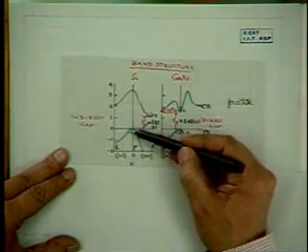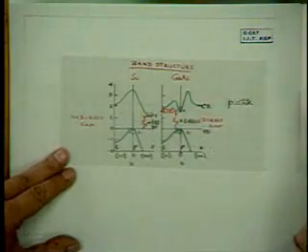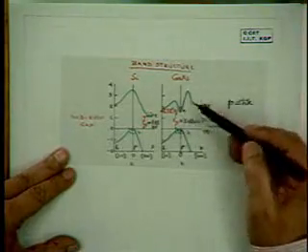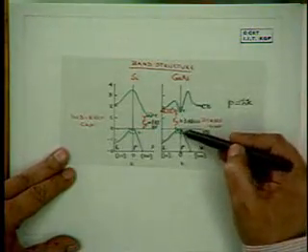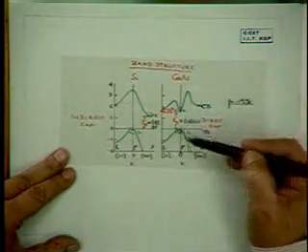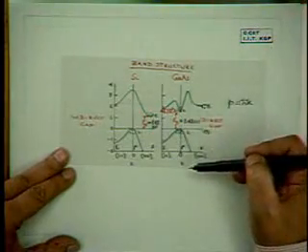So this is what is known as an indirect gap semiconductor. Whereas for gallium arsenide, the conduction band minimum and the valence band maximum are both at k equal to 0. So this is a direct band gap semiconductor.